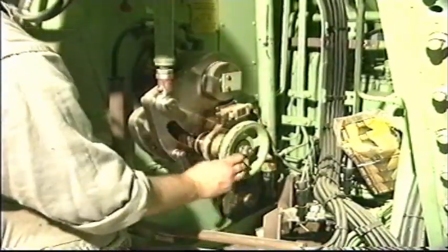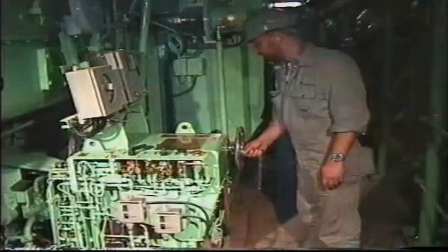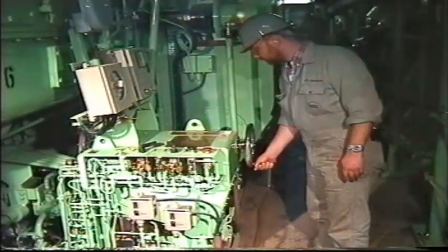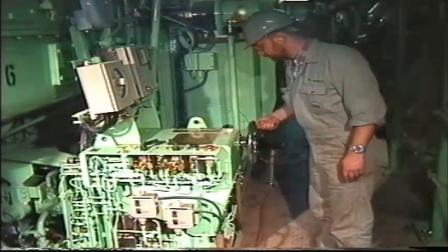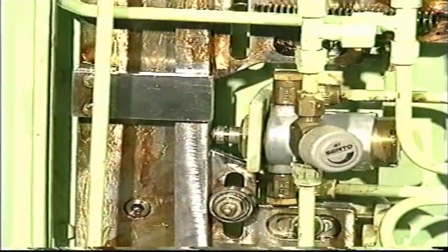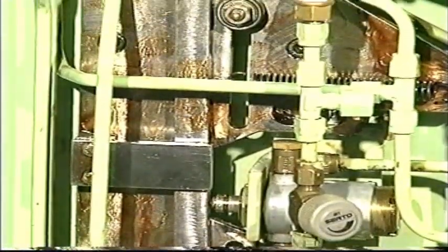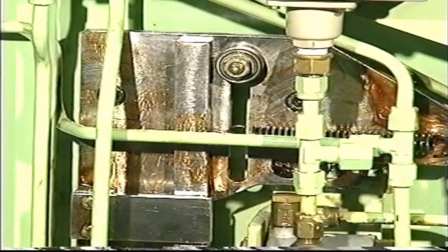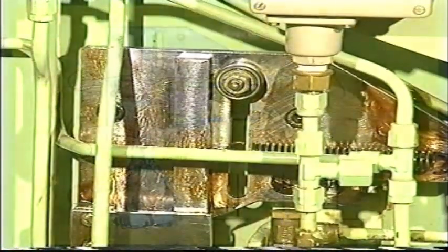Switch from engine room control to control from the engine side console. Turn the fuel regulating hand wheel corresponding to the determined fuel pump index at breakpoint. If the steel rod does not touch both pivoting points, loosen it from the shaft and turn it to the correct position.